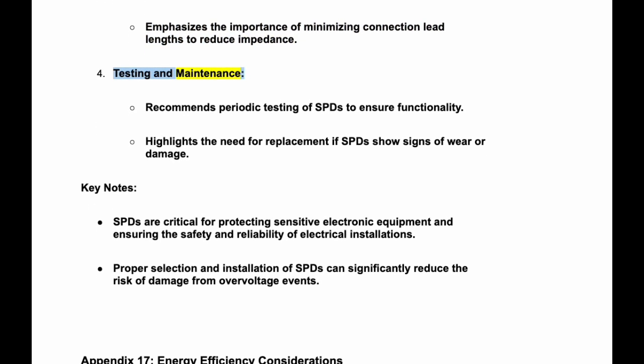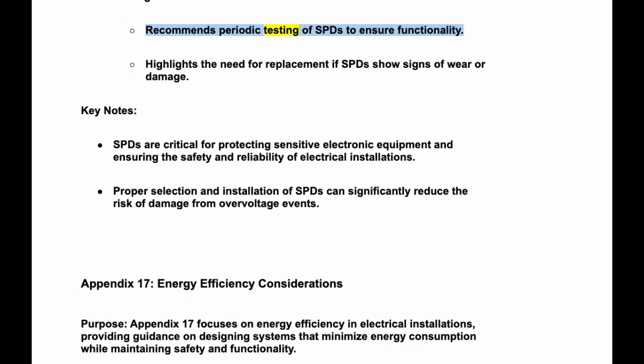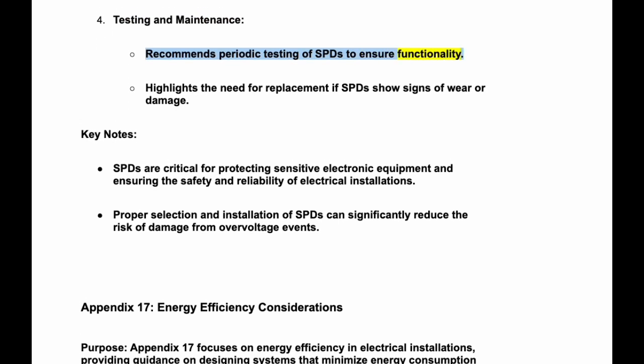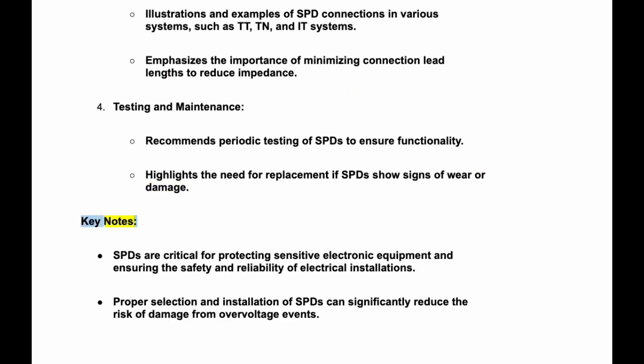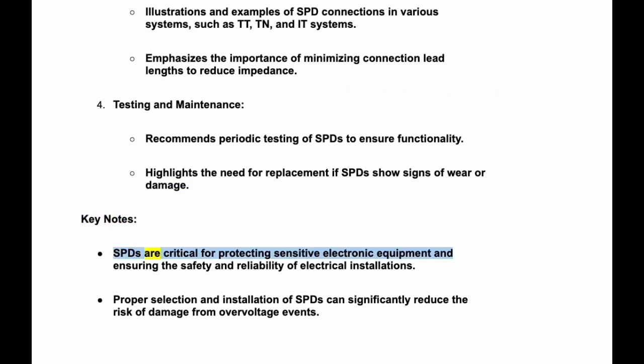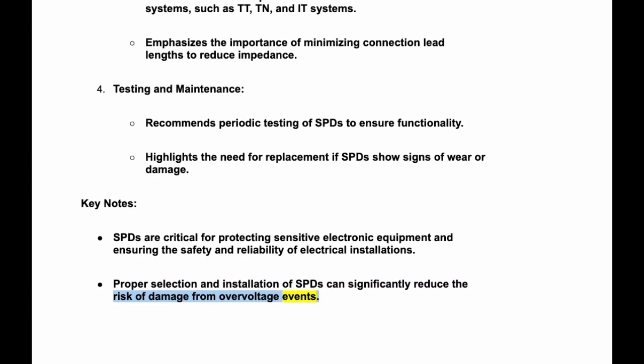Testing and maintenance. Recommends periodic testing of SPDs to ensure functionality. Highlights the need for replacement if SPDs show signs of wear or damage. Keynotes. SPDs are critical for protecting sensitive electronic equipment and ensuring the safety and reliability of electrical installations. Proper selection and installation of SPDs can significantly reduce the risk of damage from overvoltage events.